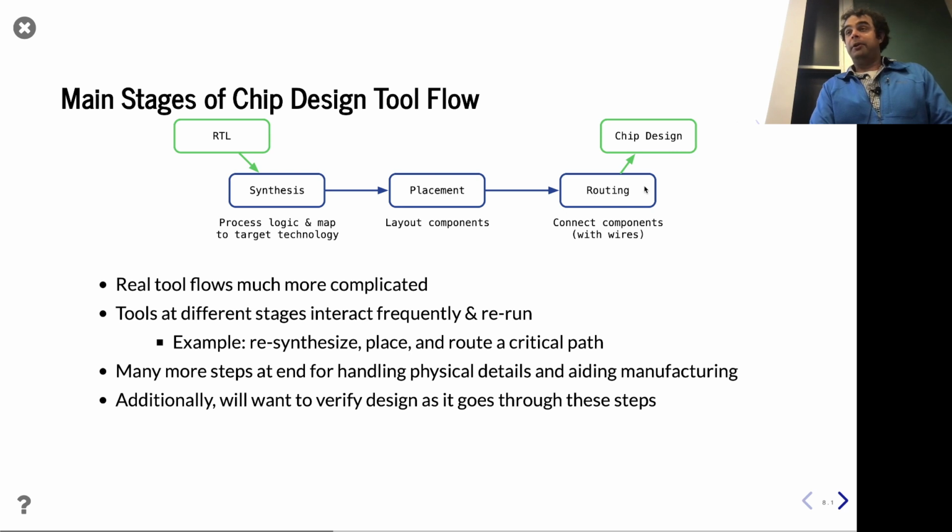And then at some point, you need to wire them all together. And now, at a high level, this is what you need to do to make a chip that functionally works, right? That works in theory functionally, right? Now, of course, there's a lot more details. After you get to this design, you want to make sure it's correct, and there's certain things you do. For example, you might do something called a DRC, or design rules check. Basically, even though you're using all these tools along the way, and it should hopefully be automated, this design may actually be unbuildable, right? And so there's a DRC program that checks your design for certain criteria, and if it doesn't meet those criteria, it's unbuildable, right?